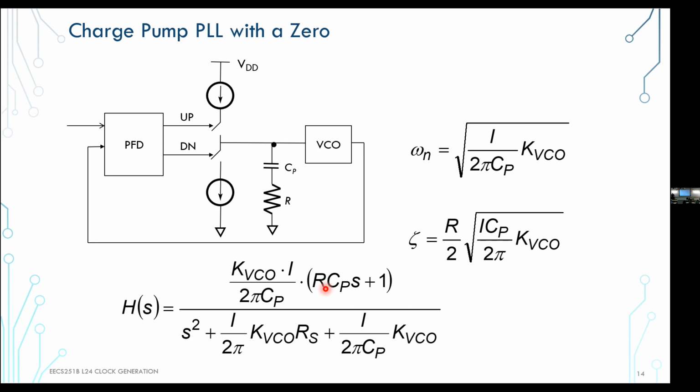Now, fortunately, there's some natural capacitance forming here that we're not taking into account, right? I did just design this loop filter. But there's some wire, there's some input referred capacitance of the VCO itself, or that control input that I still need to take into account, right?